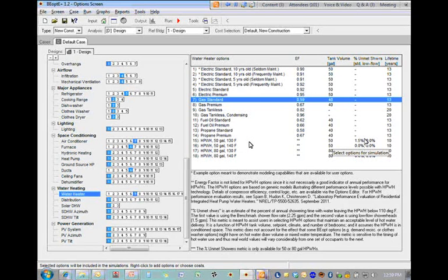So you can remedy this by increasing the set point to 140 degrees Fahrenheit, or by increasing the tank volume to 80 gallons. Or the second column of values shown is an estimate of the percent unmet showers using low-flow shower heads. So that is a third way you can remedy the situation. So there's different ways that the capacity of the heat pump water heater can be increased. So that's why we left it up to the user to select appropriate options with the guidance of this metric.